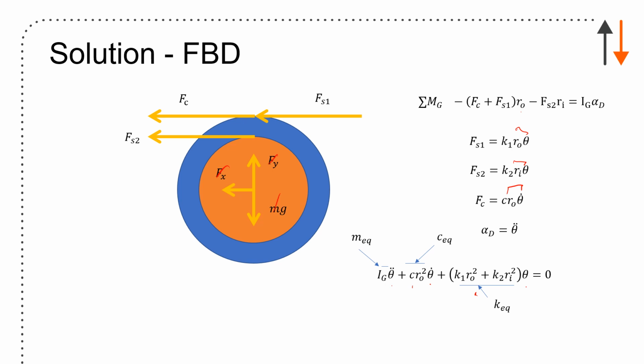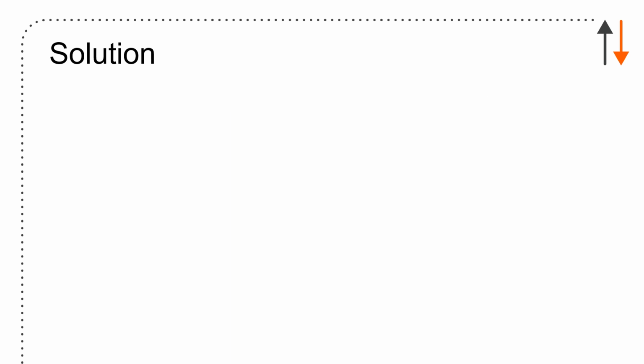Often the challenge is to recognize that the spring constant is not necessarily the spring constant of the term, and in particular in this problem, you had two moments to deal with, and that's R0 squared and Ri squared. Substitute in the definition, critical damping coefficient is twice the square root of K equivalent and mass equivalent. Put in all the terms, and you solve through.